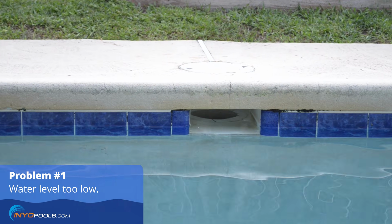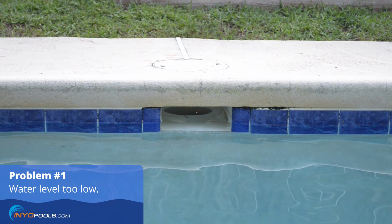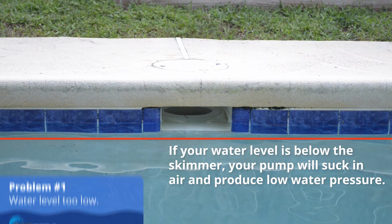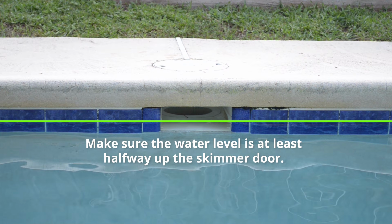The first thing to check is the water level of the pool. If your water level is below the skimmer, your pump will suck in air and produce low water pressure. If it sucks in too much air, the pump may lose prime altogether. To fix this problem, make sure that the water level is at least halfway up the skimmer door.